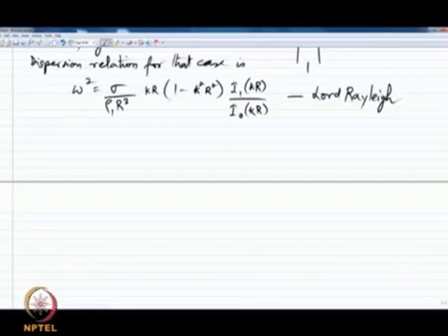So, a cylindrical jet that is infinitely long has greater interfacial energy in terms of the surface tension than liquid spheres that are discrete and arranged a spacing apart given by 2 pi by k bar in a non-dimensional way. So, this is the finding from the linear instability calculation, and this state overall has lower interfacial energy than the initial state, which is an infinite column of liquid.